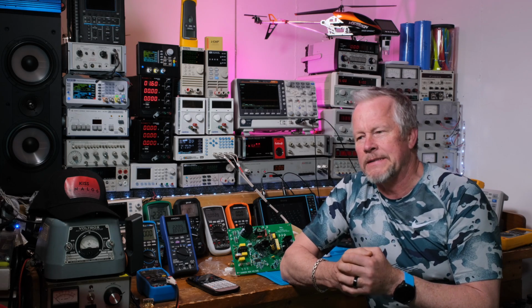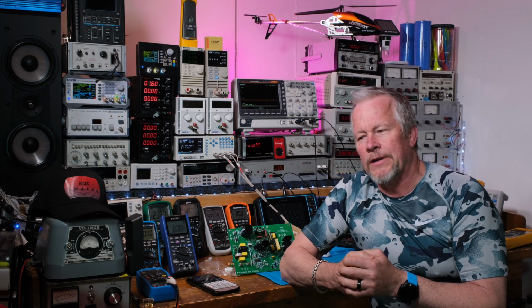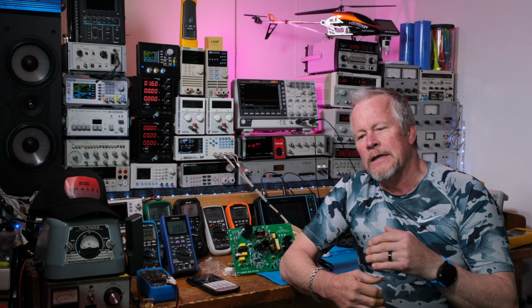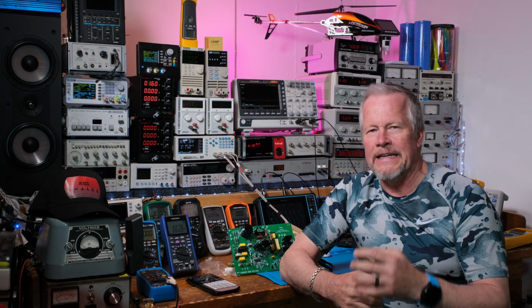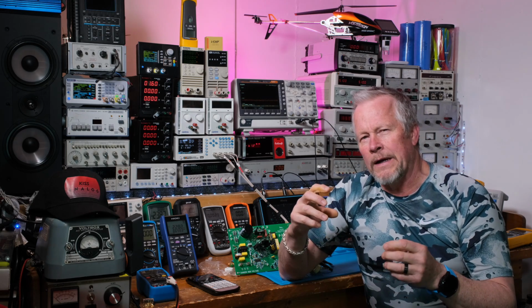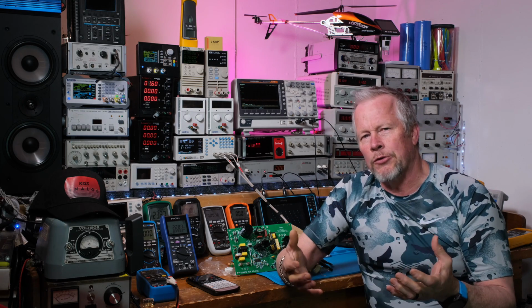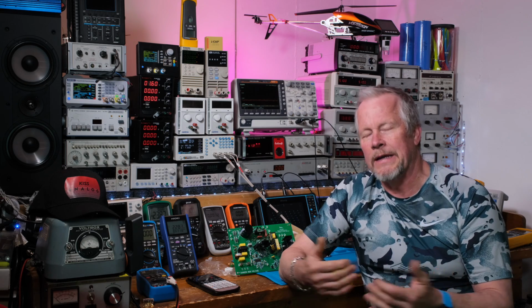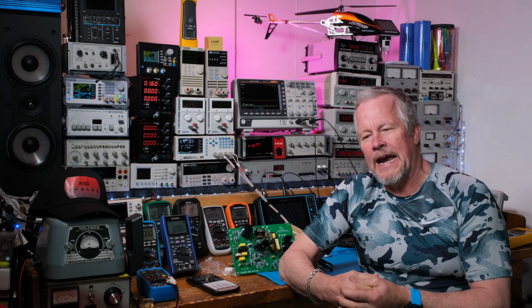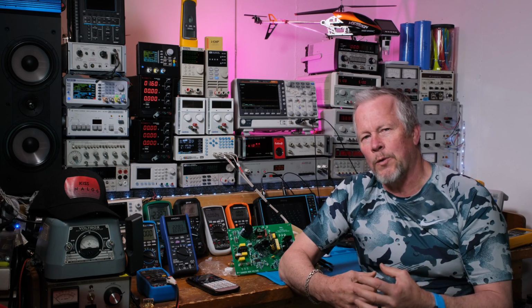That's done on purpose, so that you don't have perfect coupling, so you do have some leakage inductance, and that leakage inductance is differential inductance. So when you have your common mode choke, you also have some differential mode inductance, a little bit more, so that it works with the X caps and the common mode works with the Y caps.